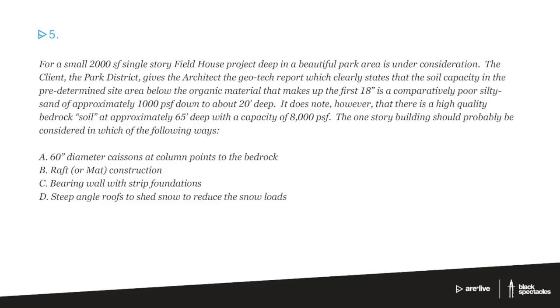But below that is a comparatively poor silty sand of approximately 1,000 PSF, pounds per square foot, down to about 20 feet deep. It does note, however, that there is a very high quality bedrock soil at approximately 65 feet deep with a capacity of 8,000 PSF.